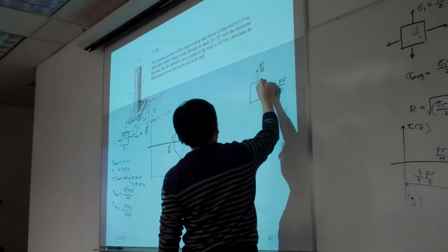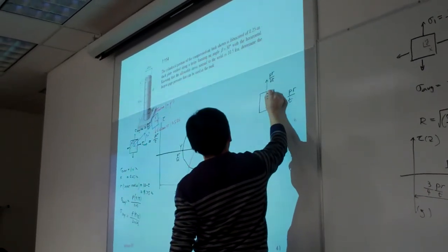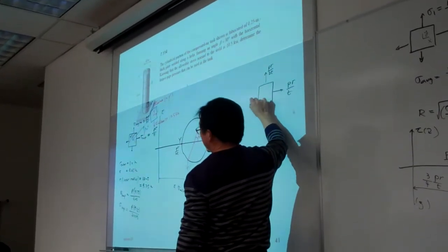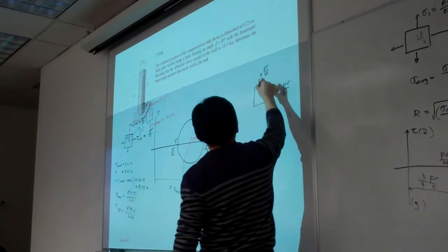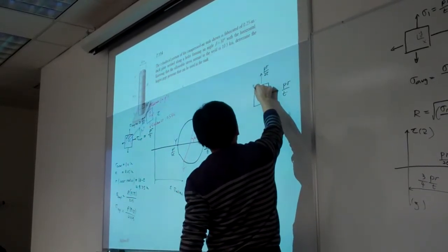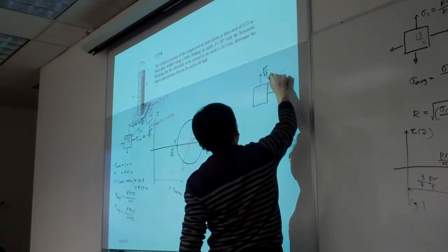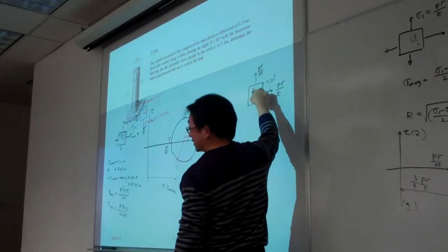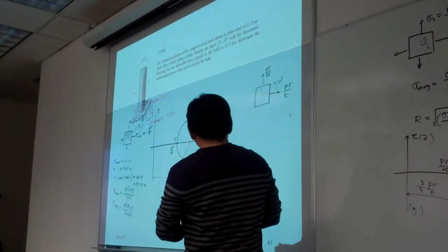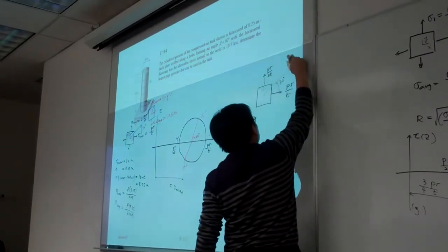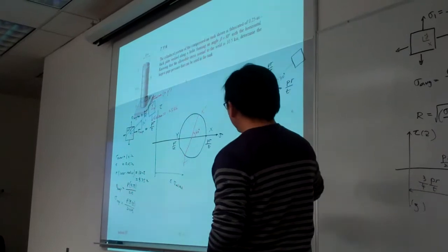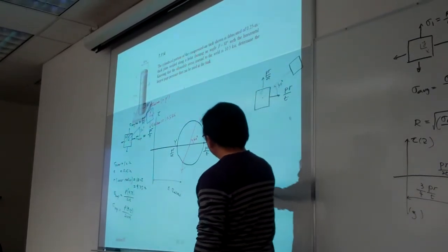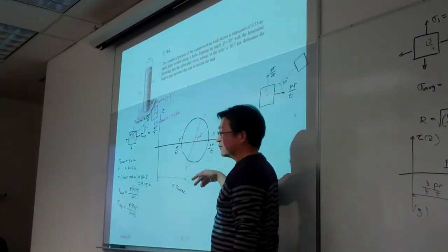From the problem statement, we know this is the welding orientation, which is 30 degrees. So naturally, I want to rotate this element by 30 degrees to align to the welding orientation. And so here I build up the oriented element like this. That's it. And then from this point onward, in order to use the information on the Mohr circle, we keep the label.